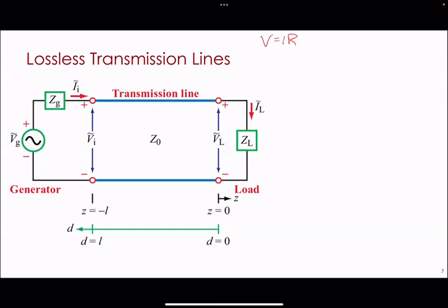If you're a millimeter away from the load, you still have distinct incident waves and reflected waves, and you could let that point approach Z equals 0. That's easier to think about than at the absolute Z equals 0 point, because there they're perfectly coinciding, it's the point at which the reflection occurs, and things get a little bit fuzzy. So I would think about it the other way, okay?